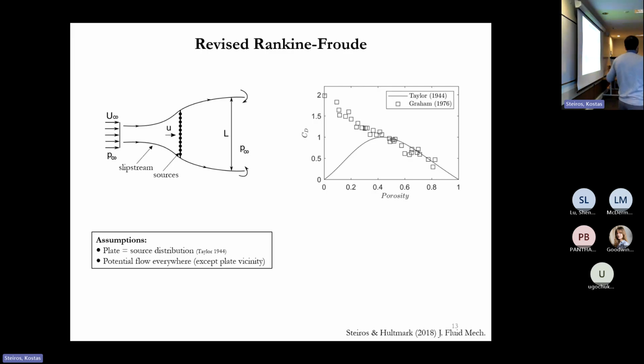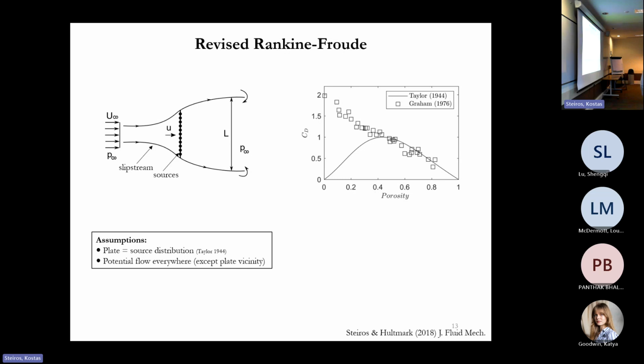Right. So a bit of fundamental aerodynamics. I hope it's not too specific. So it is potential flow theory, the one we consider, so it's quite easy. So we consider a free stream that impinges on a distribution here of porosity that can be a wind turbine or a porous disk. Right, and the idea was first by G.I. Taylor, who was a very famous aerodynamicist. It was in the 40s,